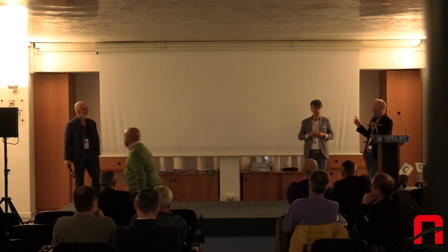What do you think? Yes, what you say is perfect. If you remember the graph that Alessandro showed, we had that depolarization. I'd like to say that from a technological point of view, this depolarization that was done before on the tubes meant we had to stop using the pipe. Those graphs were used by eliminating the protection of the plate, and we did that remotely. So today, there is the possibility of actually not protecting the plate and assessing the polarization. Out of all the measurements that we talked about, to me, this is the most reliable one.